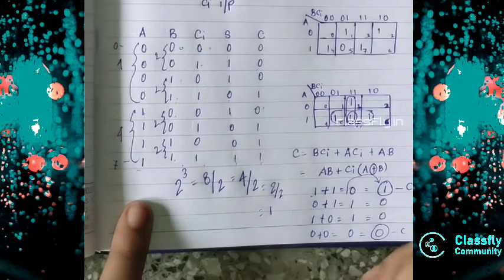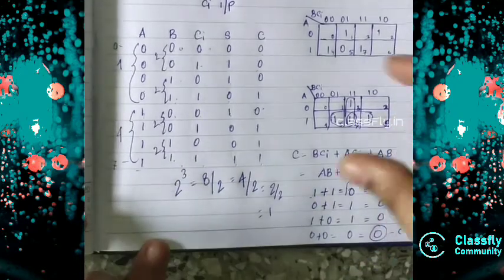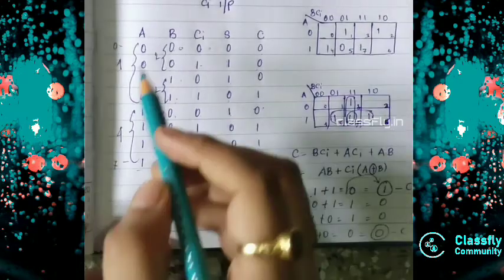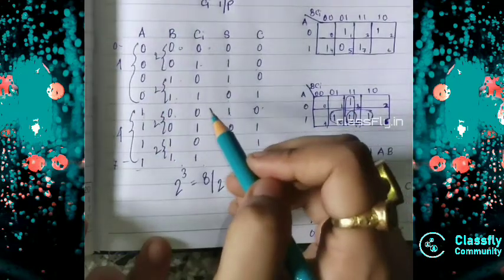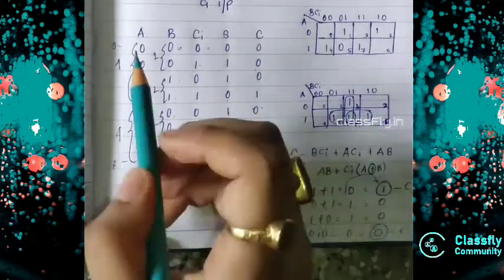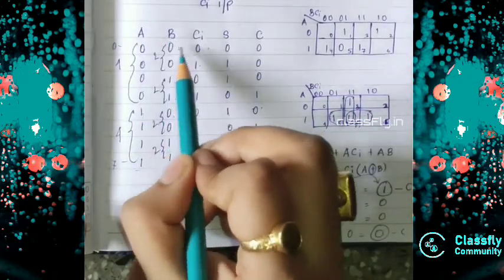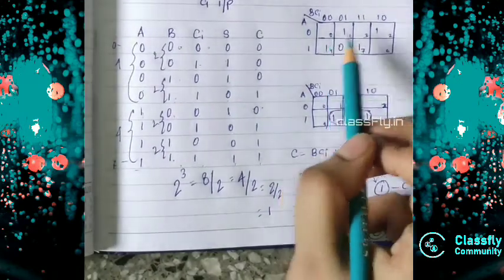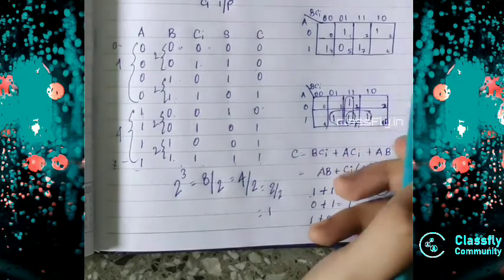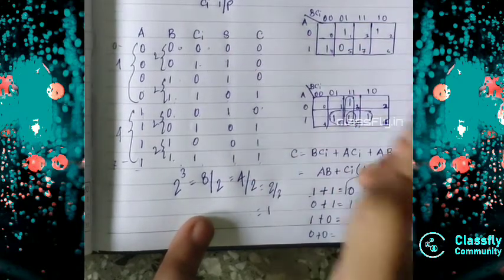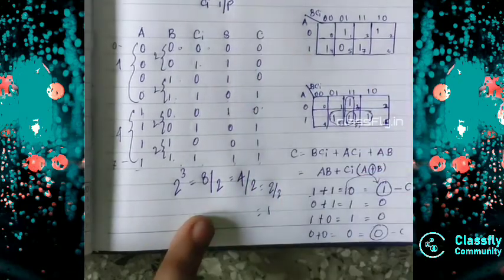So be very careful. Now whenever we can do our equations by seeing the truth table also, but prefer for the full adder do K map. As here there are 3 variables, we will use this K map, that is the 8 boxes one. So first let us do for the sum one.